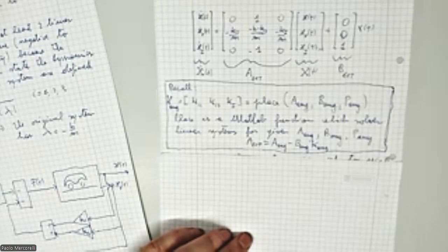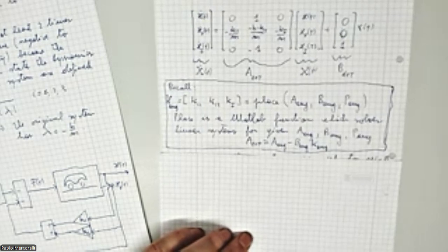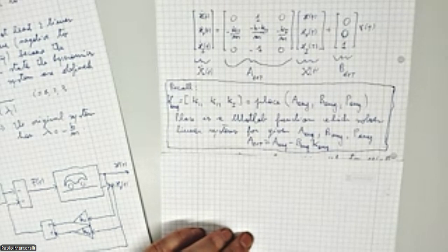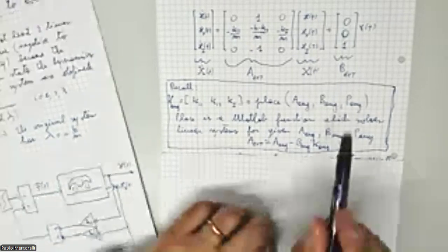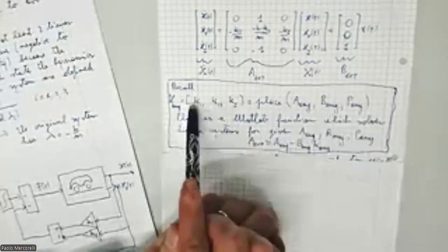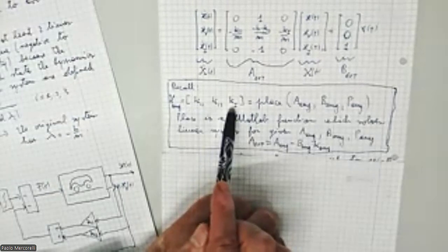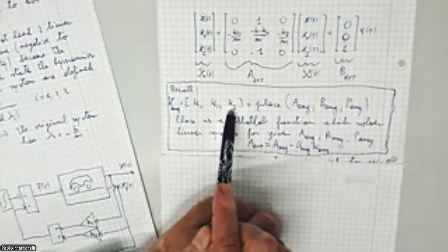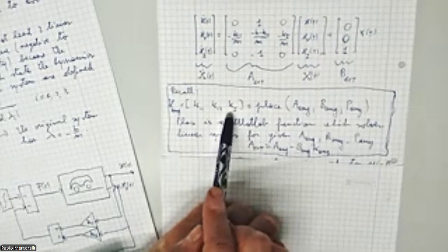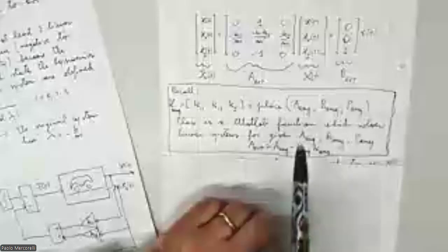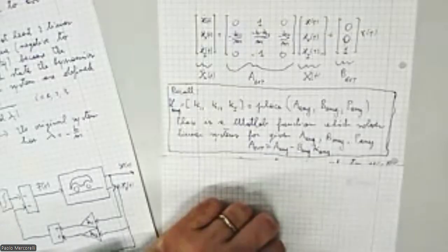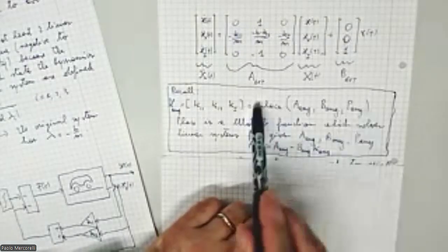Of course, this states the velocity of the control system, and this is reflected by the position of the eigenvalues. Do you remember last time? This means I have to calculate K11, K12, Ki, we will see now in detail, such that I will obtain some given eigenvalues in accordance with my specification. We will see together. We will not do it by hand, we will do it with the function place.